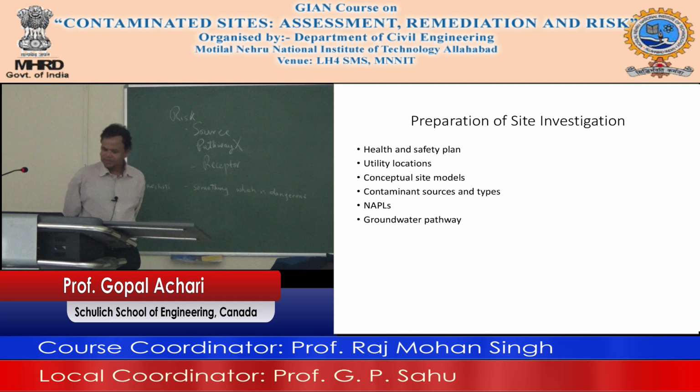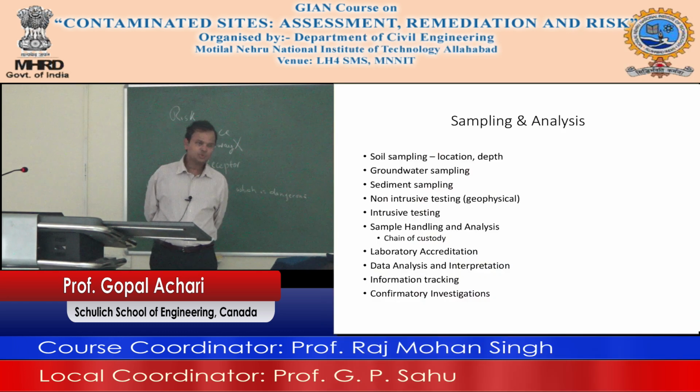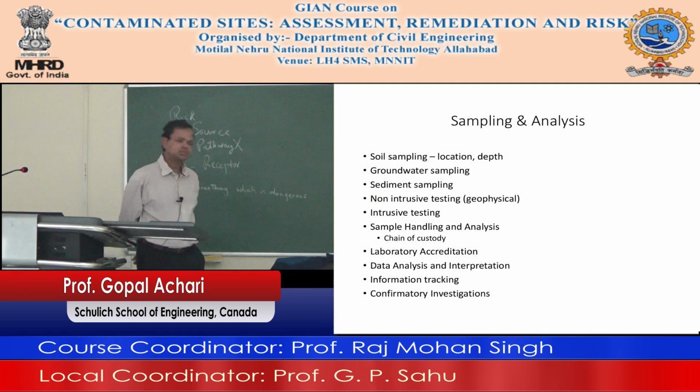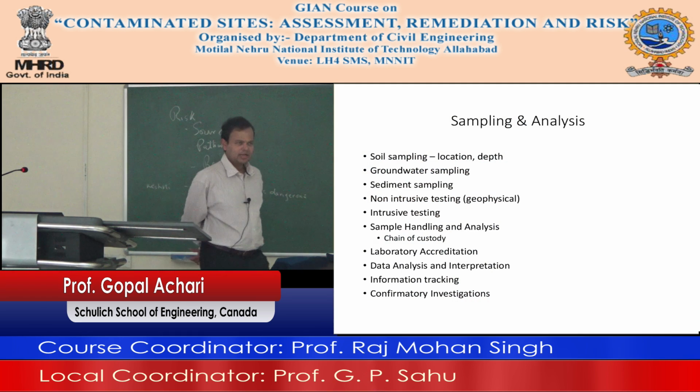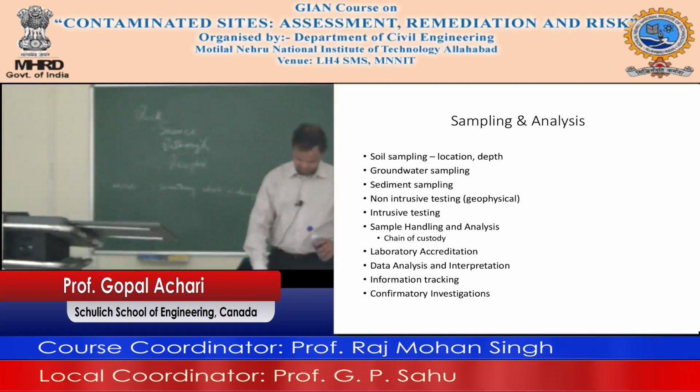Soil sampling and analysis, and groundwater sampling. For soil sampling, you need the location and the depth. When you are doing soil sampling, you also should do the groundwater sampling at the same time, unless you are just doing soil sampling on the surface. You're going to scoop. So here is the other thing: do you want to use a scoop, or do you want to auger it down?